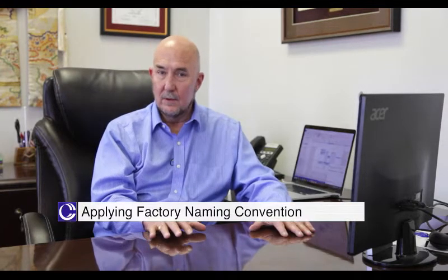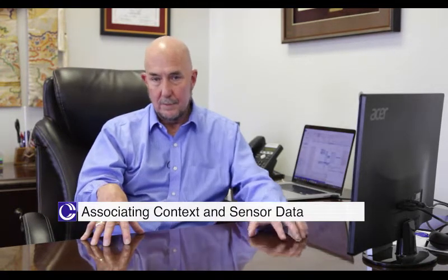Next step, of course, is most analysis applications don't want to know that the data came from different sources, and so you would need to apply the factory naming conventions in the same way to both sets of data so that the analysis applications would not have to understand the different data sources. Of course, another important piece of synchronization is knowing exactly which process chamber, which substrate, which recipe step was active at the time the data was sampled, because all of this context information is necessary to line up the sensor data with the equipment data collected at the same time and under the same conditions.